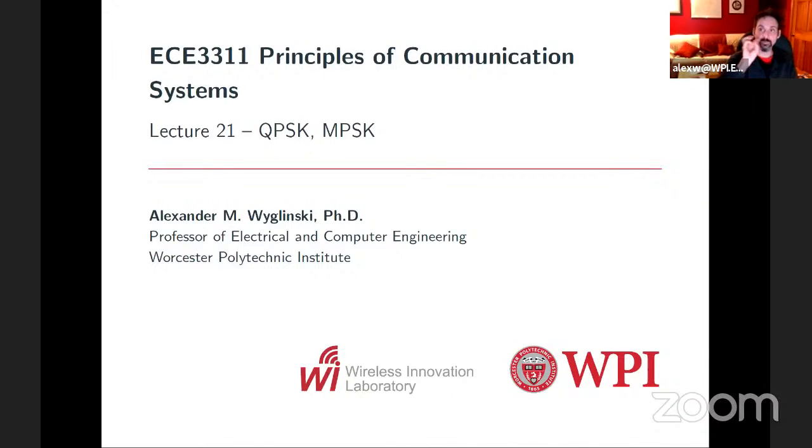And what we do is we make a unique waveform, right? First in baseband, but then it gets modulated up to a passband frequency. And that is what gets communicated over the air to a receiver that will attempt to guess, well, I call it guess, but it really tries to detect what amplitude, what phase, and what frequency, because as we'll see, we can make combinations of that. And we can try and figure out what the transmitter sent, and then from there, decode back to the binary pattern. Okay.